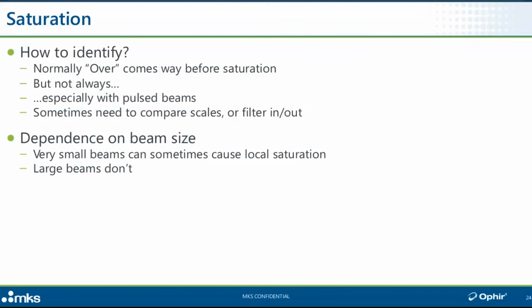Typically, the scales are divided by orders of magnitude. So let's say after the 10 milliwatt scale, the next scale down in sensitivity is the 100 milliwatt scale. So you switch to that. And now, lo and behold, you do see 8 milliwatts. Now, normally, you're not going to choose the 100 milliwatt scale to measure 8 milliwatts. You'll choose a 10 milliwatt scale, again, assuming that you have one, because you don't want to be too near the bottom of your scale. Obviously, a 10 milliwatt scale would be a better choice for measuring 8 milliwatts. But on the 100 milliwatt scale, you'll still measure the 8 milliwatts.